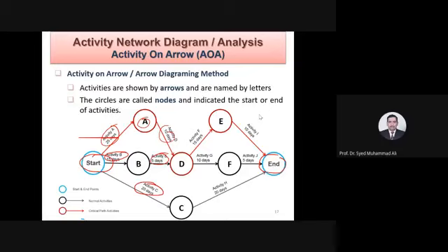for example, if it makes sense, and activities are differently planned and doing the same. So for the same project, there can be sort of infinite solutions. So you can't say why it is like this. It depends upon the particular project at hand, how you're going to sequence it. But anyways, this is the arrow diagram method, and these are the activities. Activities are shown by arrows.